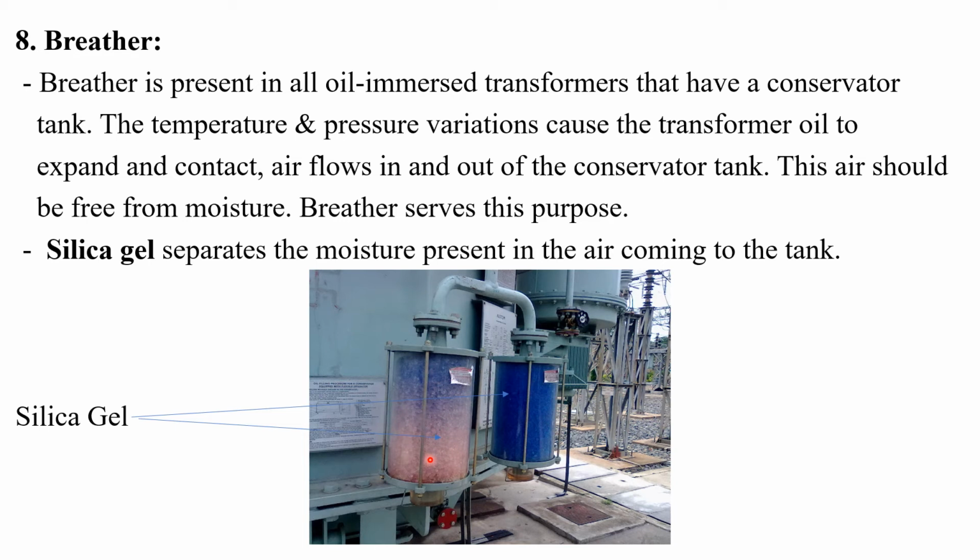Now it is in pink color, so we must replace this silica gel with pure silica gel. Its color must be, normally it is blue. Okay, in this way we can identify the silica gels and the amount of moisture present in this breather section.